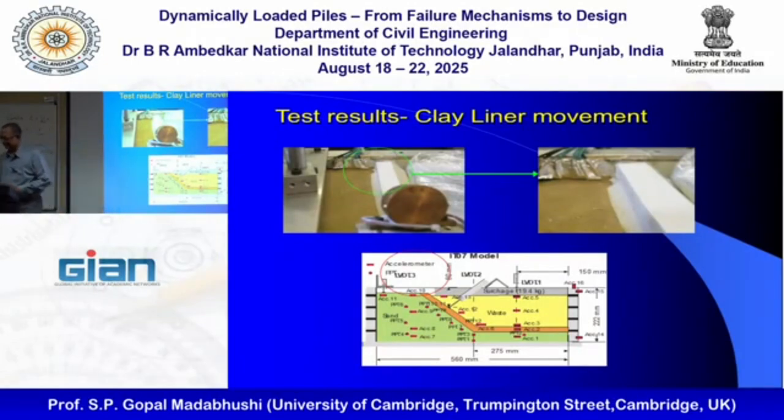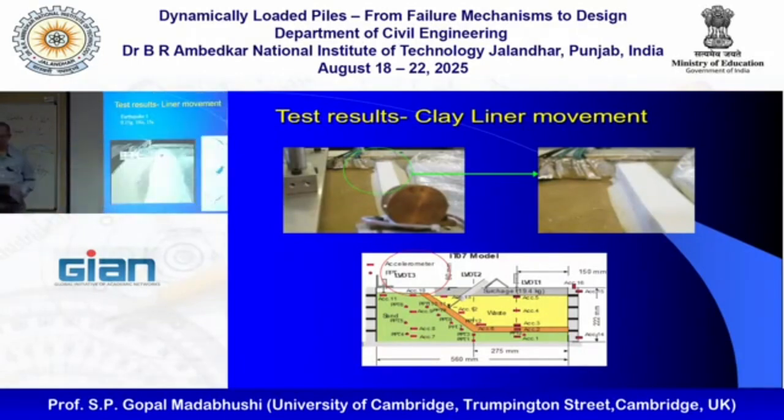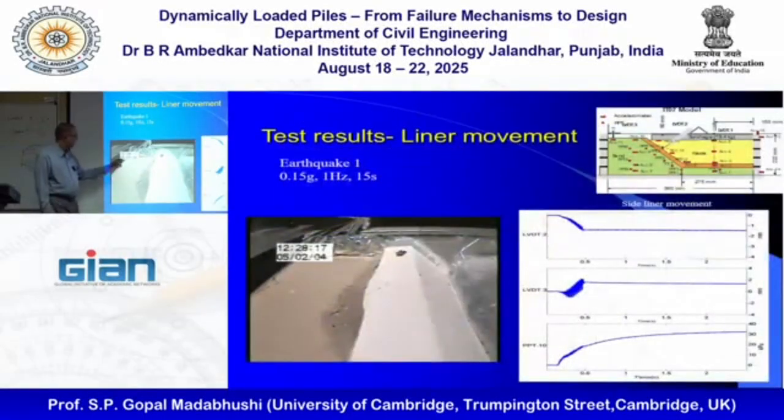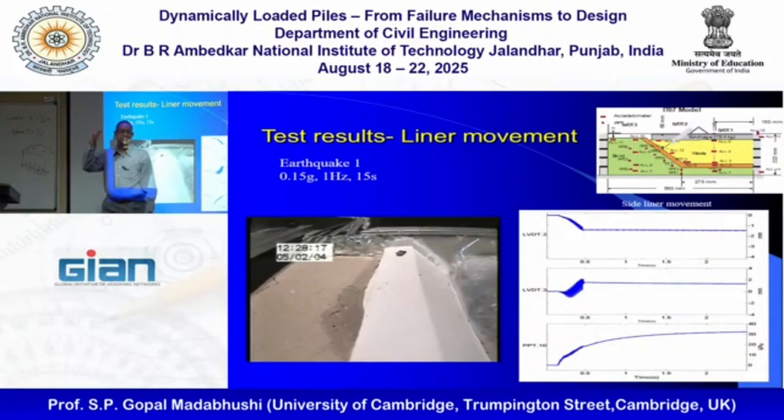Post-test, this is an in-flight picture, obviously. We could see the soil here has now gotten wet because of the pore pressure generated below. The water came up and created these kind of sand boils behind, because we held the water table about here, and so the water coming to the surface means there has been liquefaction.